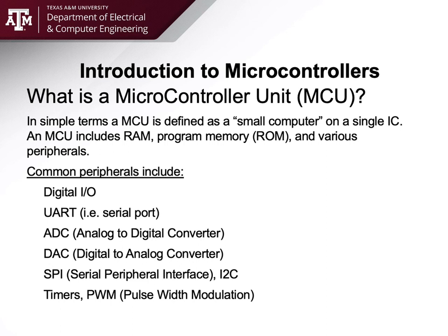Then there are things like analog to digital converters, where you take an analog signal and convert it into a digital form, sample it. If some of you have had ECEN 444, digital signal processing, you'll know a little bit about what that is. But if you haven't, you're likely to use this because if you're trying to read any sensor technology, such as a temperature sensor or a pressure sensor, you're going to want to convert that analog waveform you get out of those sensors into a direct digital signal that you will do some sort of intelligent processing on.